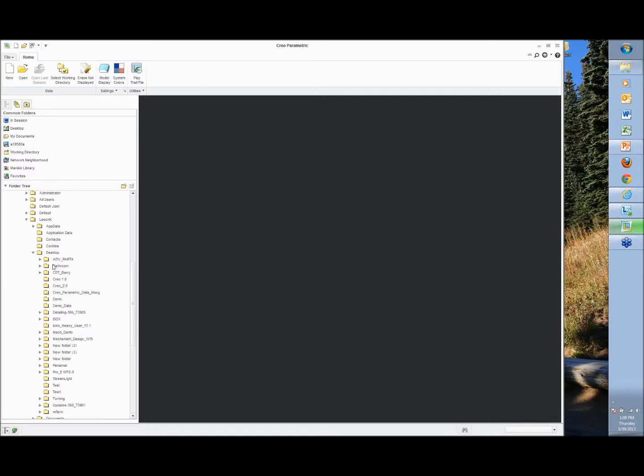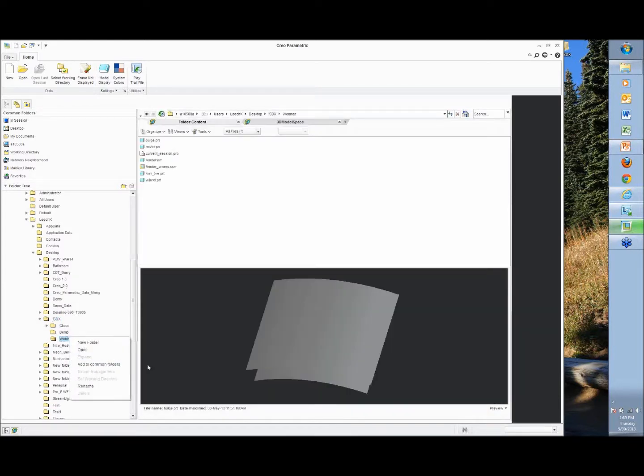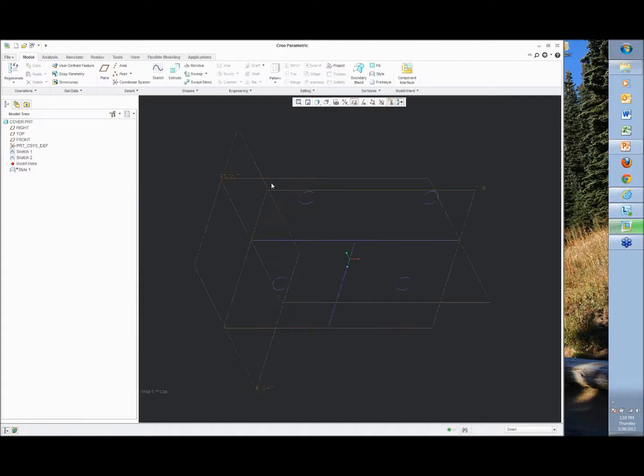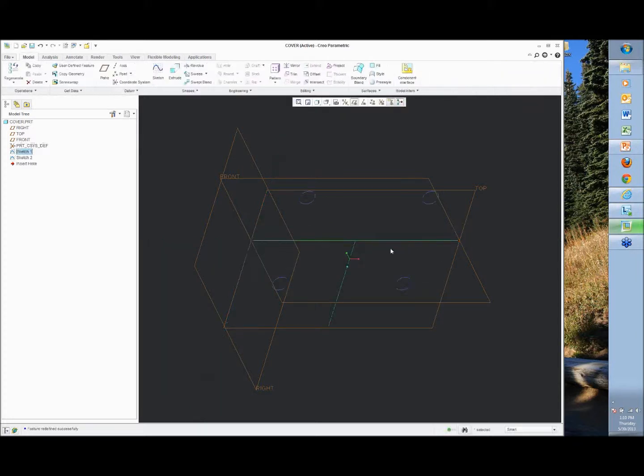Like I said, I've got some stuff set up here that I was going to work through. And the first one is let's build a little cover here, right? So this is going to be just a cover model at the end. And I got a couple things. I'm going to delete that one. I got a couple things already pre-built. I built a simple sketch with some parametric dimensions, and I'm going to connect my surfaces to these almost like a skeleton deal where I can control the shape of my model through the length of this.